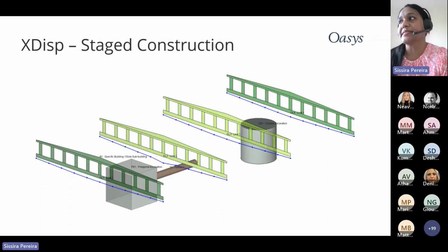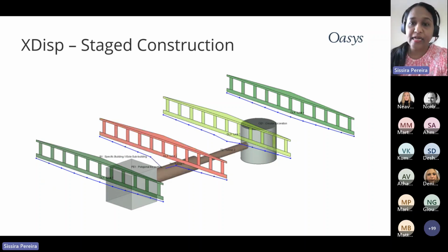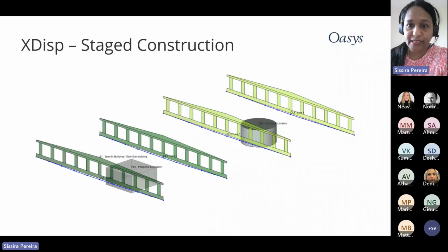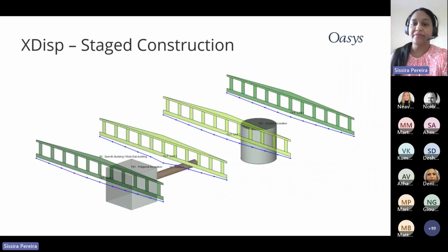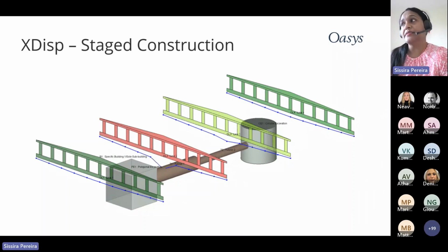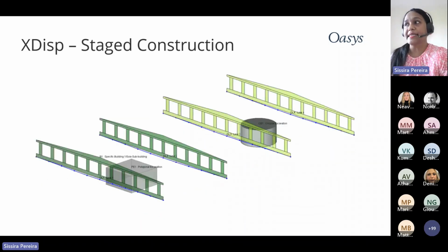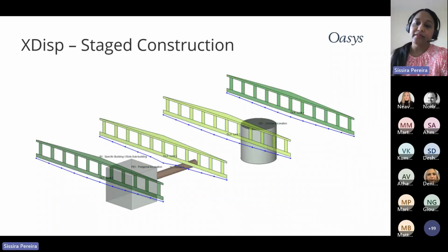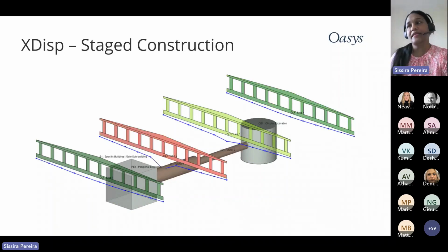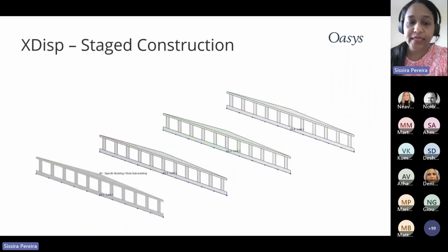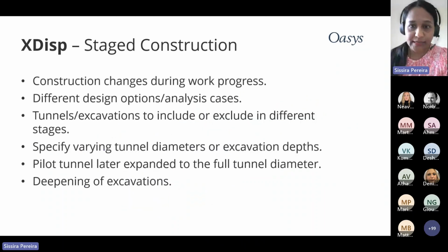category. So when we start modeling a project, the existing building might be in a category which is safe or negligible, but when the construction proceeds or the tunnel is enlarged, then the building might become into a severe damage category. So this has to be considered in the project works.